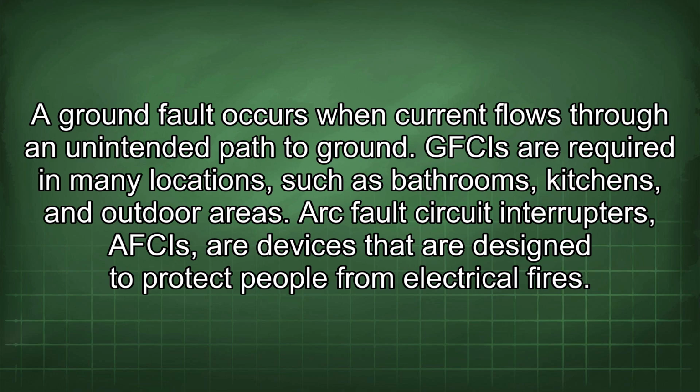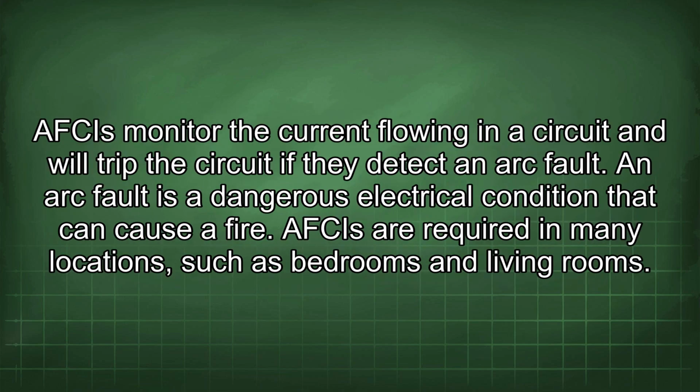Arc fault circuit interrupters, AFCIs, are devices that are designed to protect people from electrical fires. AFCIs monitor the current flowing in a circuit and will trip the circuit if they detect an arc fault. An arc fault is a dangerous electrical condition that can cause a fire. AFCIs are required in many locations such as bedrooms and living rooms.